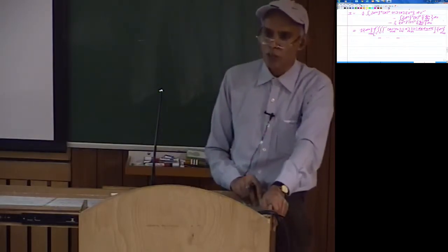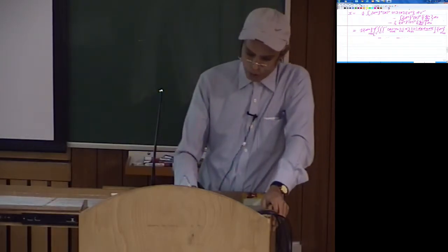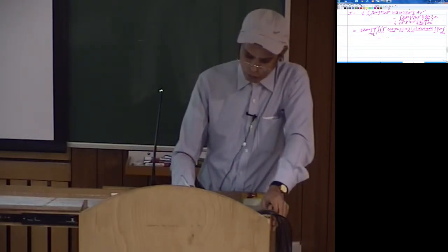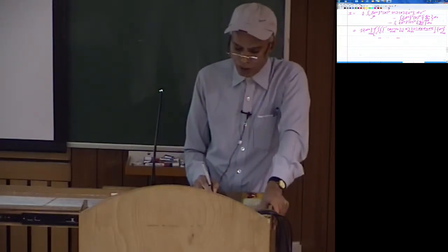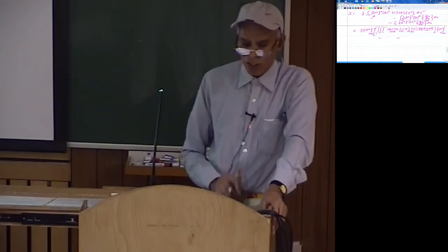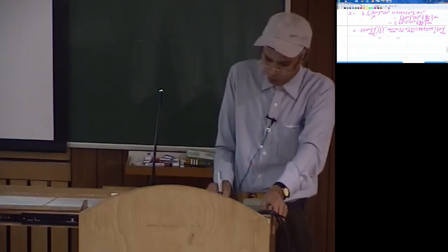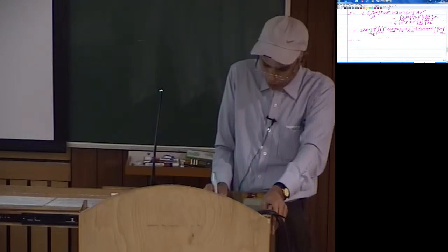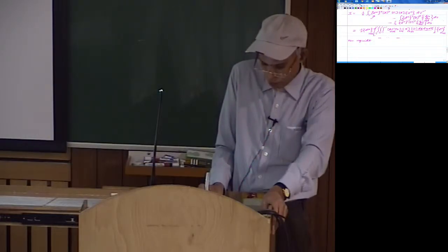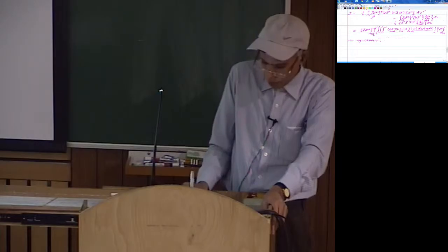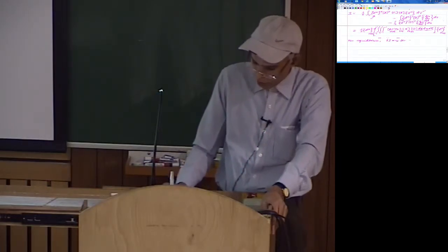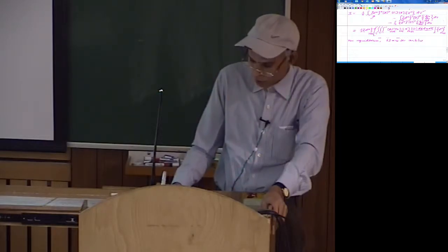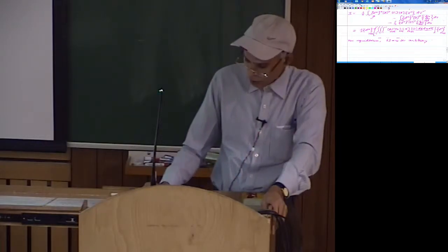Now again see here, when we develop the element level governing equation, for equilibrium, for arbitrary delta dE, this delta I, that is the variation in the integral functional, should be equal to 0. So now for equilibrium, delta I should be equal to 0. Arbitrary means it is not fixed, we can vary delta dE arbitrarily. This delta symbol is for variation.